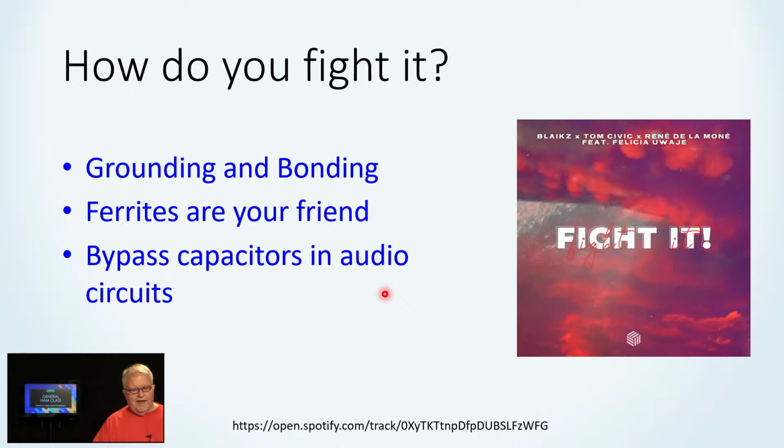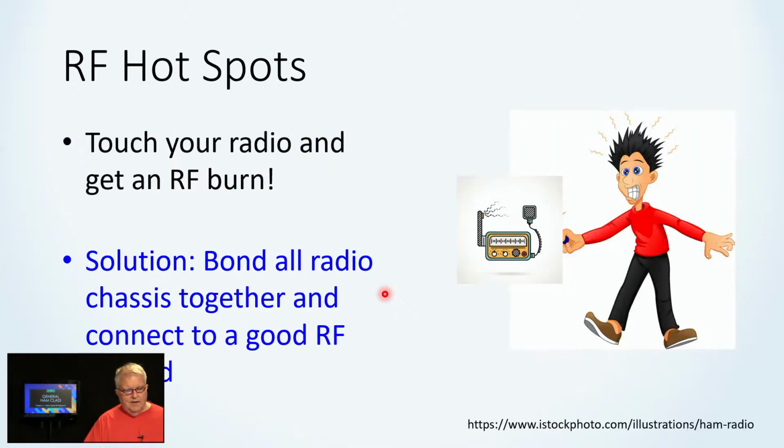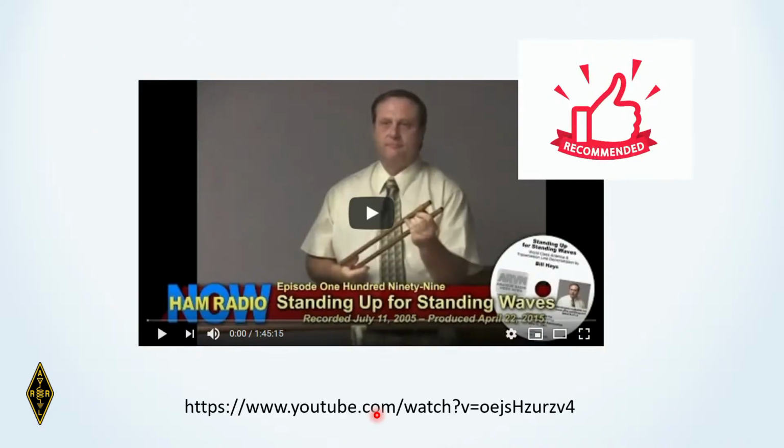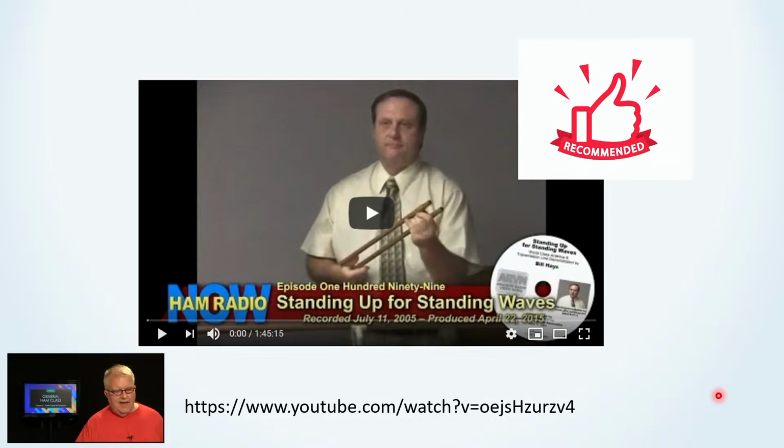Now, the worst case is when you transmit and you touch a piece of equipment and you get an RF burn. That can happen, and so again, the solution is to bond all equipment together. I'm going to send you this link, and I'll mention it also in an email. This is an excellent video to watch called Standing Up for Standing Waves, done by Gary Pierce at Ham Radio Now.